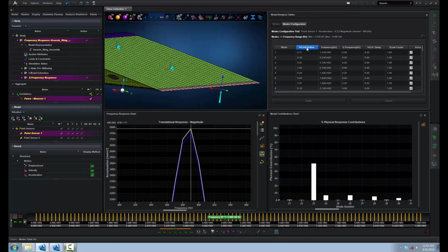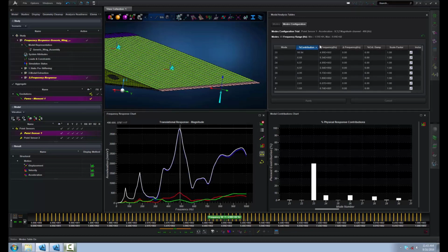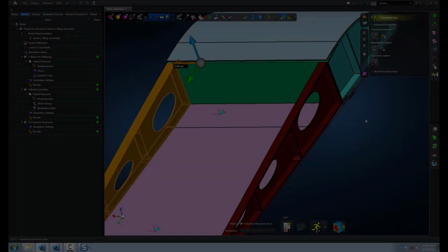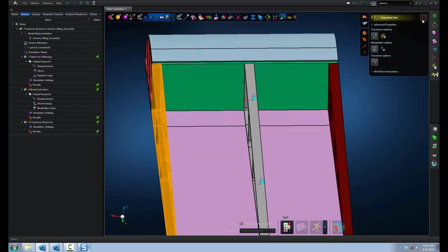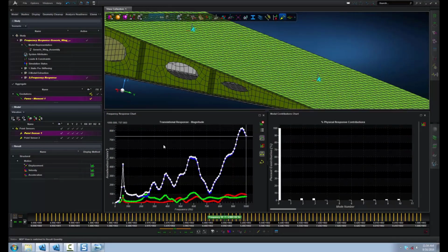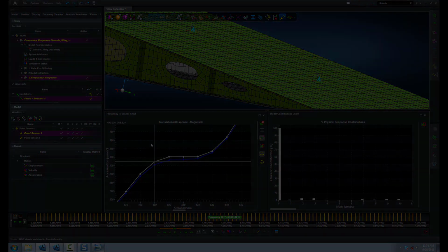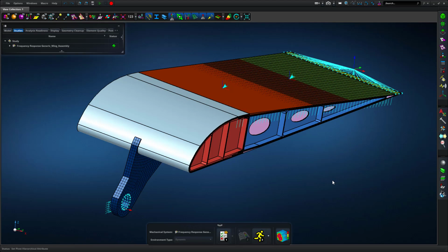world to Apex Fossa. The demo that we showed back then walked the user through how to look at the dynamic signature, find an anomaly that we needed to fix, do a what-if study, and then once we figured out what to change, we could go back to Apex pre-processing and add a stiffener to reduce that resonant frequency, and then rerun finally to verify our new design. Now let's take that one step further.